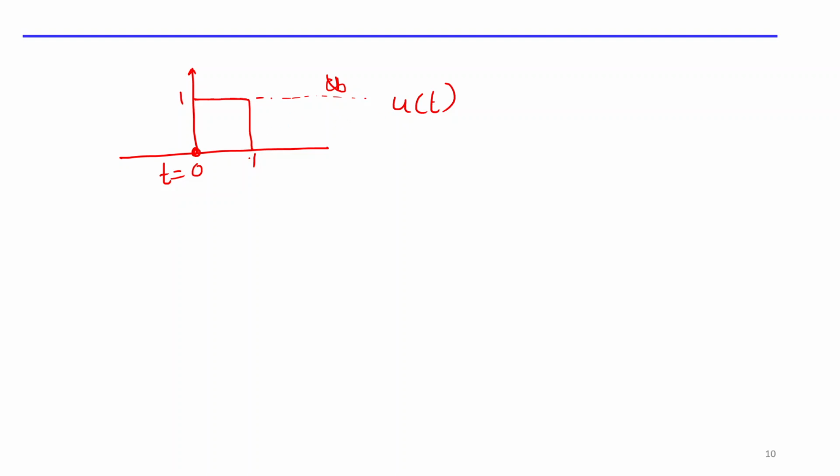Okay, but you see that there is another person sitting at t equal to 1. He is not allowing you to go in this direction. What he is doing, in place of that, he is pulling your leg down and going in this direction. It means whatever the height you are here, 1. Remember, whenever square signals and rectangle signals are there, don't take the slope, always take the height. But whenever ramp signals are there, always take the slope. Now here the height is 1 and u of t, this is 1 times u of t, so 1 is 1 only, that's why I'm writing u of t. So u of t means it is a signal like that up to infinity.